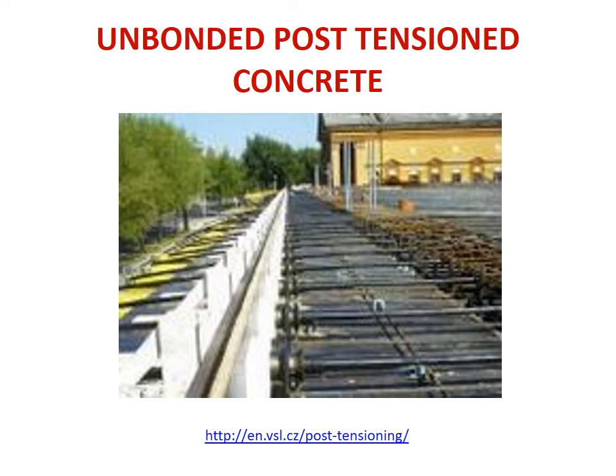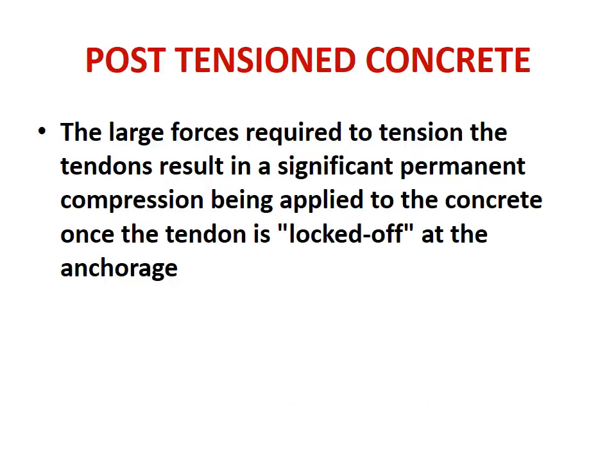Unbonded case, you can see the sheath, and then this is not counted. And then the large force required to tension the tendons results in significant permanent compression being applied to the concrete once the tendon is locked off at the anchorage.